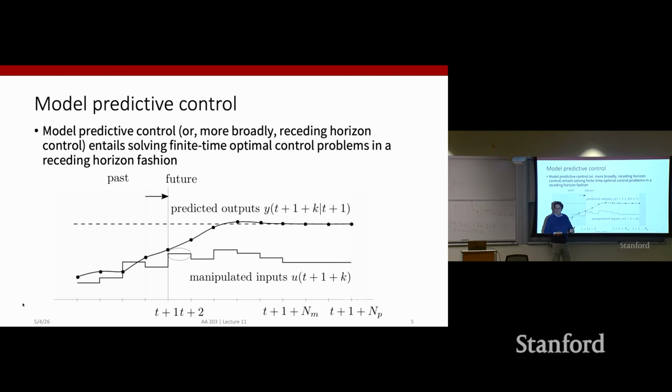The idea is that at every single planning cycle, you always solve an open loop control problem. But since you replan, which means that you get to observe a new state, and based on that, you solve a new open loop optimal control problem, you actually endow the entire framework with a notion of closed loop, because you are closing a loop on your most recent observation of the state. But you're always solving an open loop control problem.